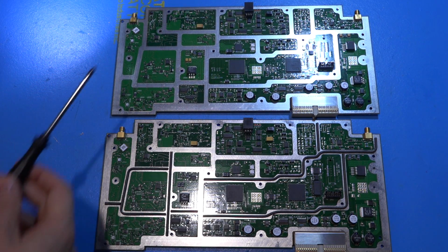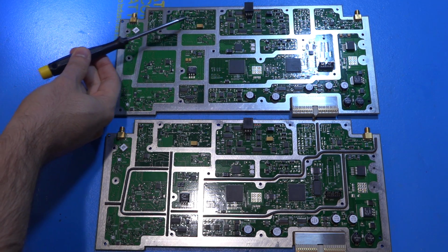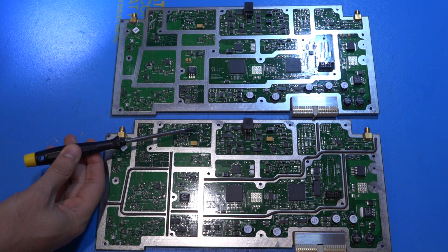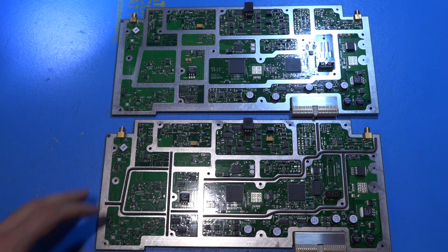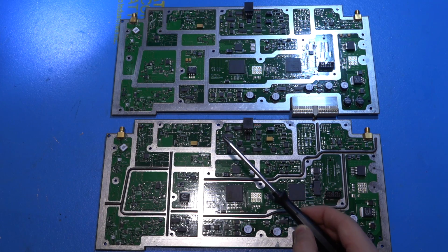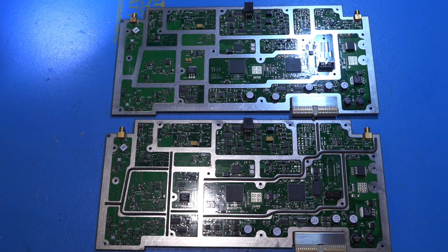I took the transistor from up here, which is the same transistor that's in the core of the VCO, and I moved it into the transistor of the VCO of the board that I'm trying to fix. I also measured every single one of the diodes. I took them off, I measured them, and two of them measured a little bit different than the rest. So I replaced them with two from this board.